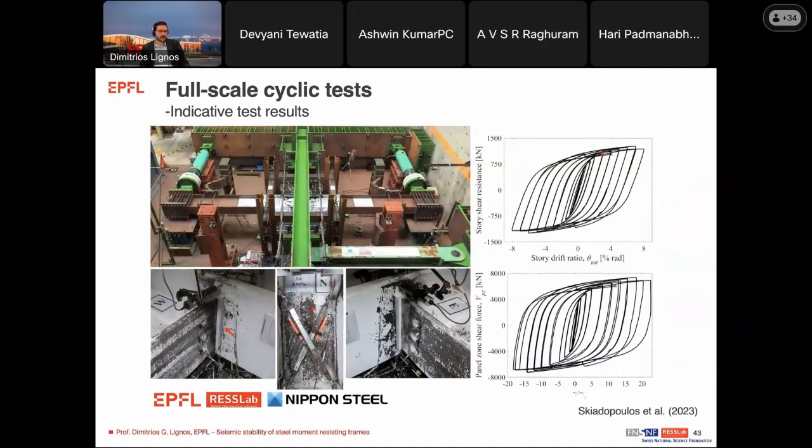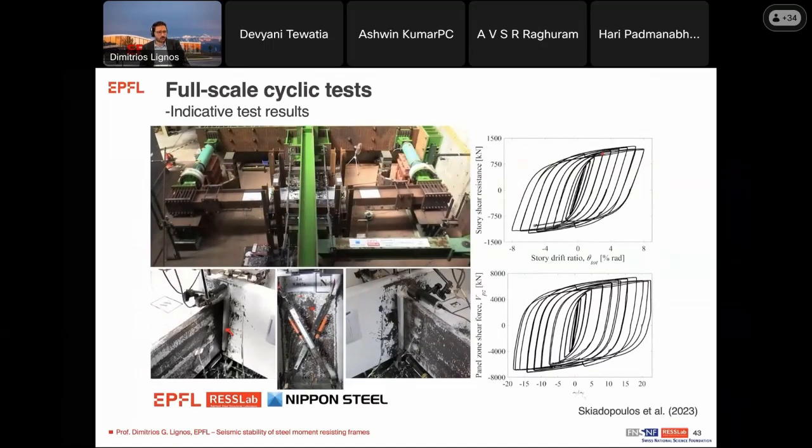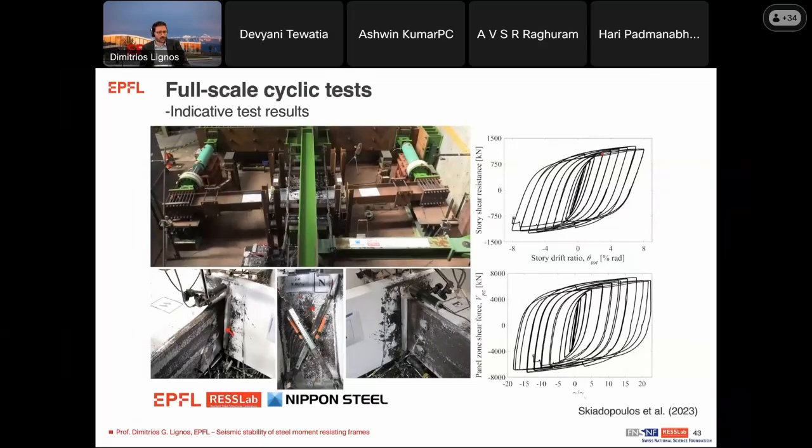And here, this is an example where you see that the beam to column connections designed with panel zone joints exhibiting shear yielding could in fact demonstrate superior performance relative to what we actually do today, including also the potential use of beveled backing bars that minimize fracture potential at this position.